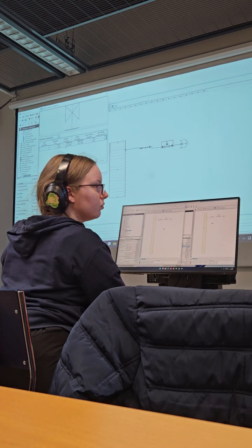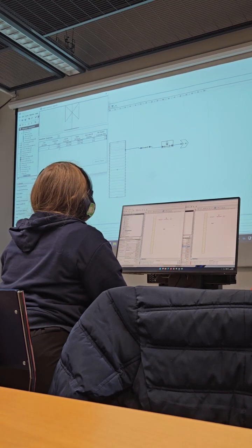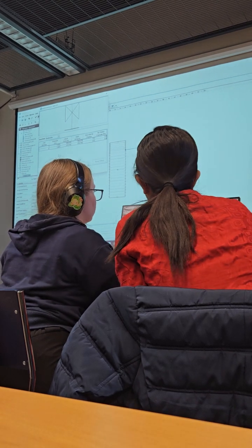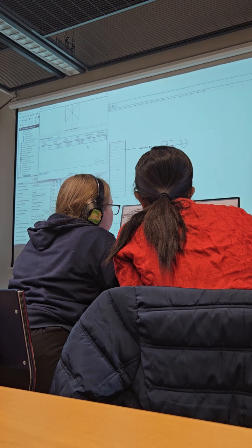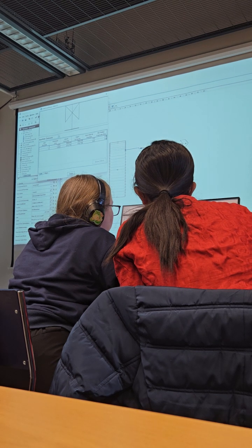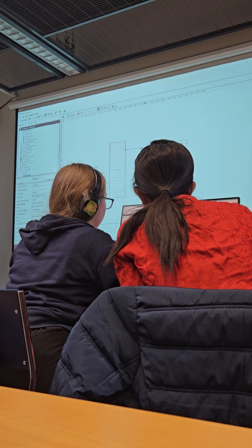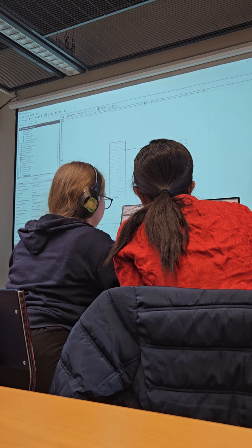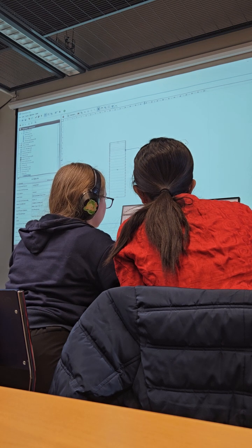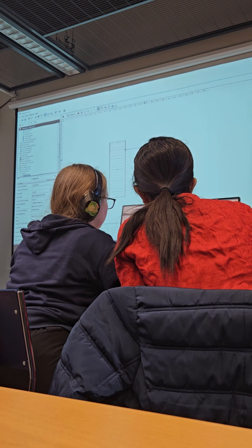So the temperature here is not really important. It is only the pressure difference that this is looking at. So for pipe 20, the gas volume fraction is also 1, because we assume that the level is below this, so it's all gas. Okay. But for this model which I'm building now, it's not correct because I do it quickly. You should check every detail though, so that they match with the instructions.